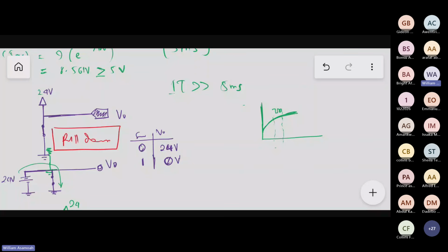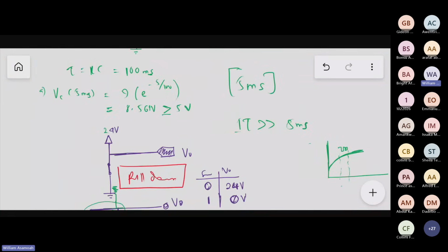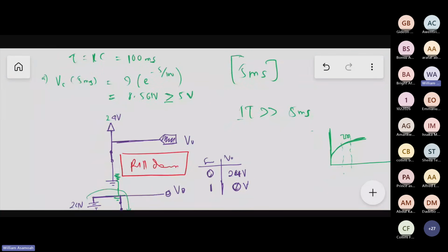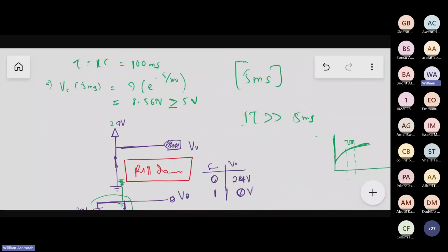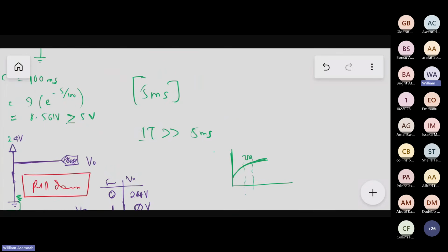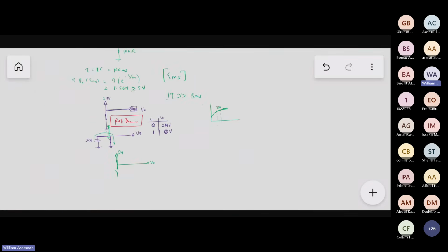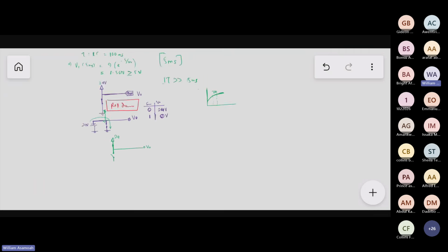For a PLC, any voltage lower than 1 volt, at times it's 1.8 volts, but here the question asks us to use 1 volt, is a low signal, and the machine will turn off. So let's calculate how long it will take to decay from 8.561 volts to 1 volt, when the PLC would see it as a low signal.